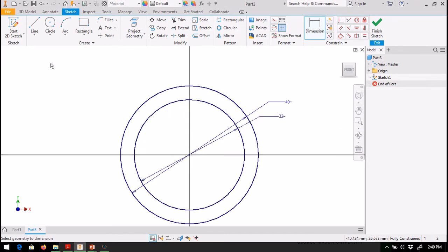Okay, now up here I'm going to select construction, and create a few construction lines to act as reference axes. So I want to create another line out here, and let's make sure that we set the 60 degrees between them.